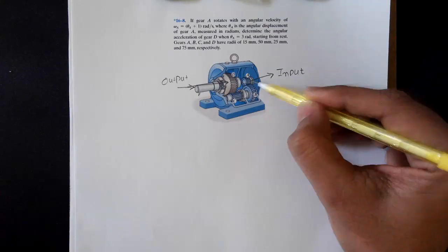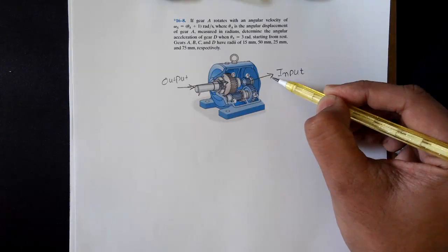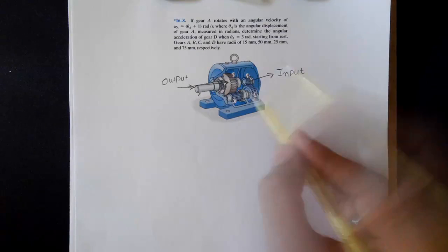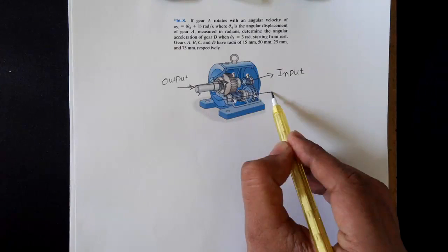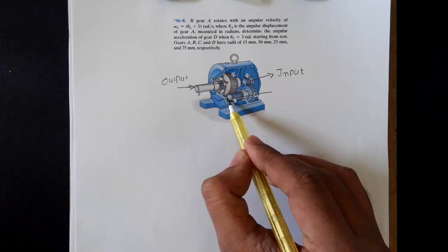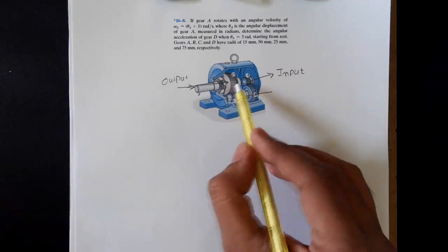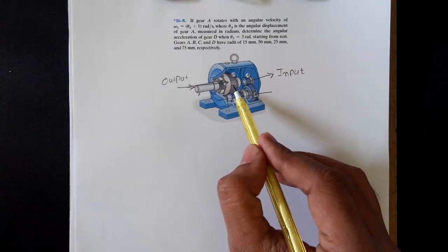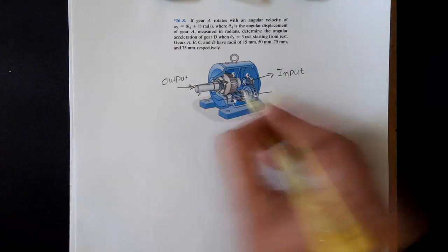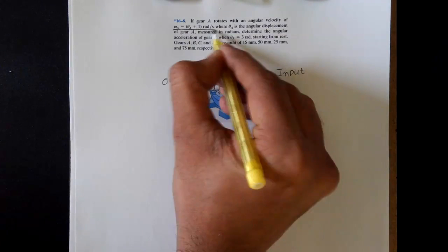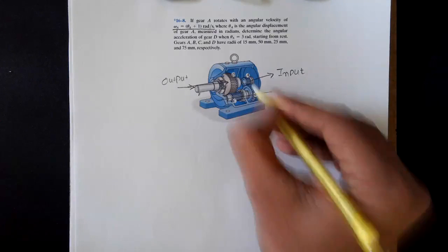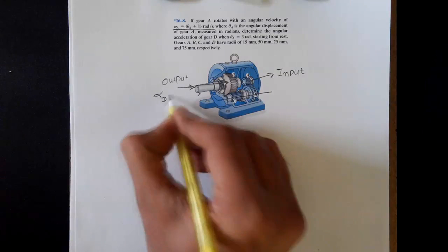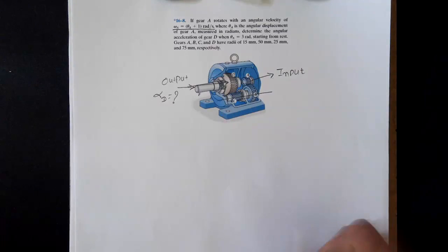Gear A is mounted on a shaft which is driven by, let's say, an engine or electric motor. Gear B is in mesh with gear A, so B is driven by A. Now gear B and gear C are mounted on the same shaft. That means they both have the same angular velocity and the same angular acceleration. And gear D is driven by gear C, so it will have a different angular velocity and angular acceleration. What we need to do in this example is, we have been given the angular velocity of gear A as a function of angular position. So that is what we know for gear A, and we need to calculate the angular acceleration of gear D by using the calculation.